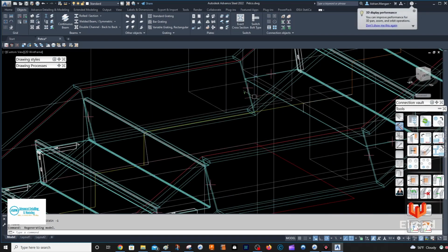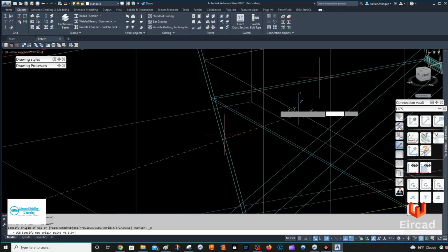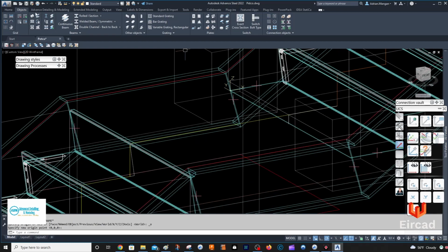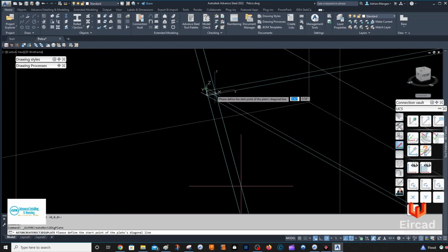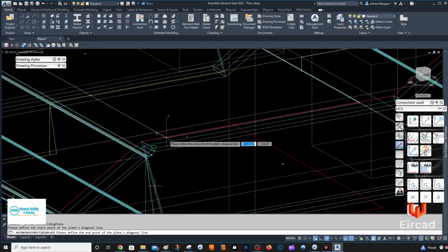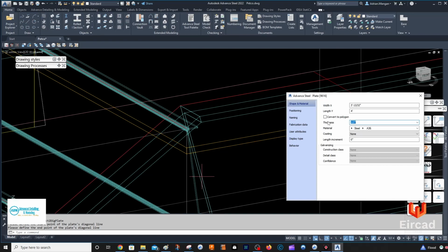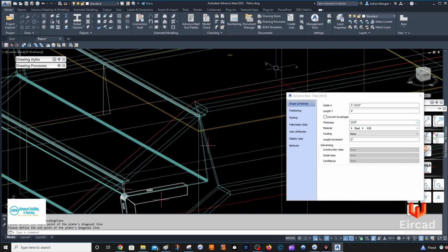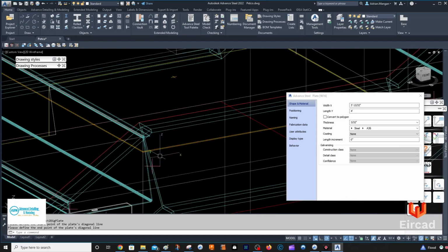and then you can just come up here and create a plate. If you want to create a plate up here, you're going to put some angles in, so you can set your UCS up here, and then just go to home, and if you go here, it gives you the opportunity to do a plate. So select this point here, and then I'm just going to come over there like that, and it's going to be 30 seconds. We can see that it's good there, and it's good there, and it's hitting on the front, which is fine, I don't care.